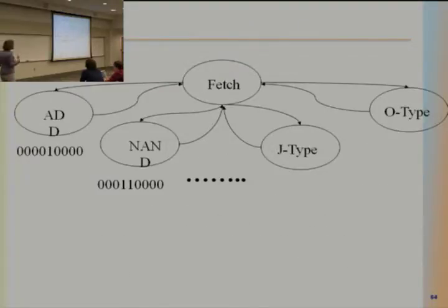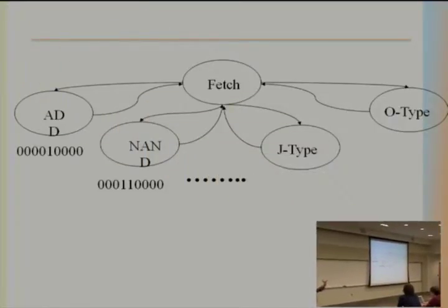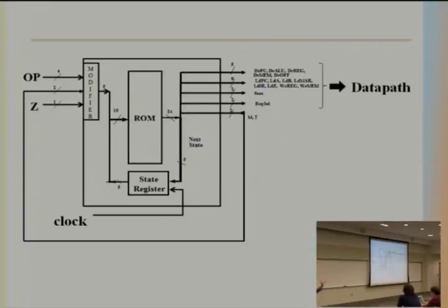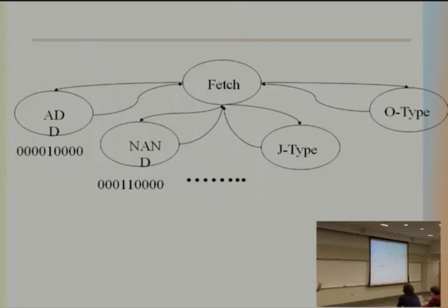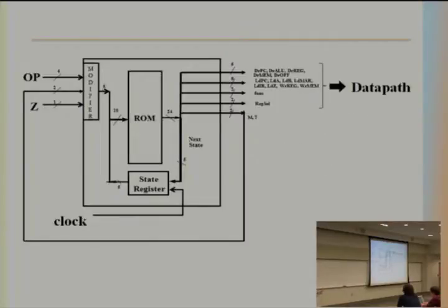And on top of that, you have to code each one of these instructions, basically. Because if you have a branching and within a branching you want to do addition and so on, you may want to add, in front of those 5 states that we had for this state register, code for these instructions, which are 4 bits. So if I take those 4 bits and I put Z as a bit, and then I use my 5 bits for just different states that I can be in, that will give you a final control unit.